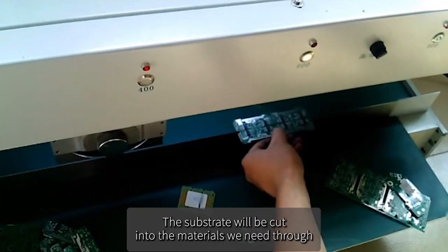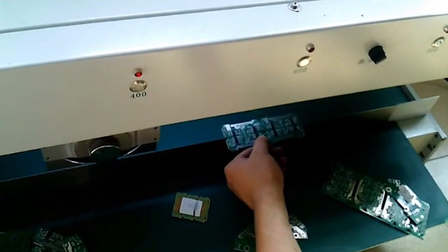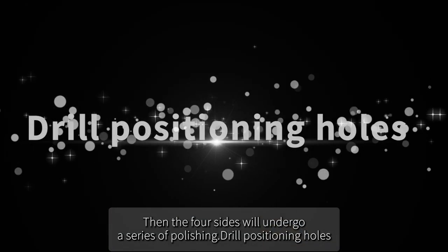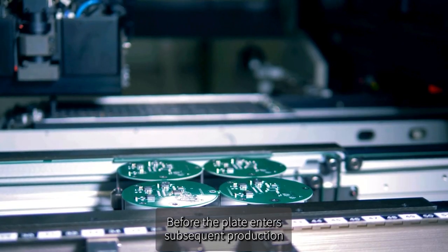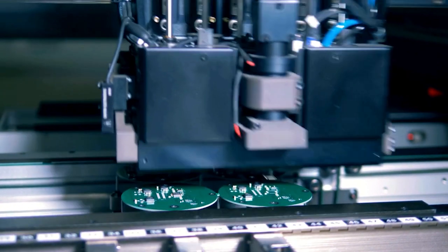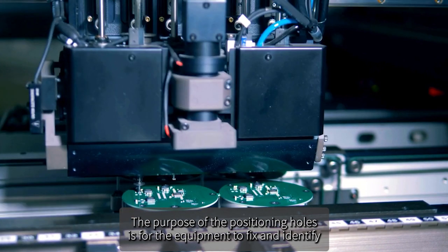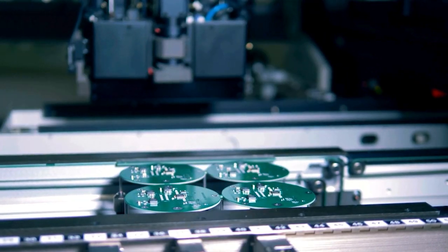The substrate will be cut into the materials we need through a machine called a cutting machine. Then the four sides will undergo a series of polishing. Drill positioning holes. Before the plate enters subsequent production, positioning holes need to be drilled on both ends of the plate. The purpose of the positioning holes is for the equipment to fix and identify the relative position of the plate during the subsequent processing.